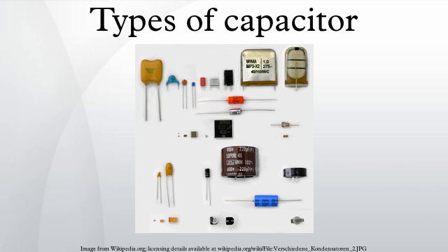Comparison of types, electrical characteristics, series equivalent circuit. Discrete capacitors deviate from the ideal capacitor. An ideal capacitor only stores and releases electrical energy, with no dissipation. Capacitor components have losses and parasitic conductive parts. These imperfections in material and construction can have positive implications such as linear frequency and temperature behavior in Class I ceramic capacitors. Conversely, negative implications include the nonlinear, voltage-dependent capacitance in Class II ceramic capacitors or the insufficient dielectric insulation of capacitors leading to leakage currents.